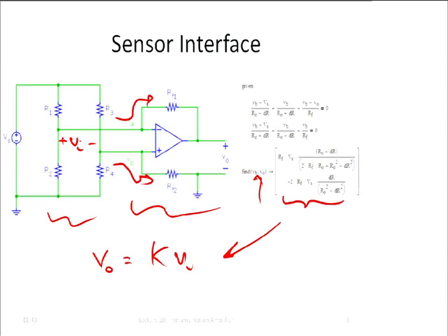Yeah. You put a big resistor there. Okay, we could make these two resistors really, really big, and then maybe the current that would be flowing would be smaller. Huh? Yes. Put a simple non-inverting op-amp at each point where we measure VI. You mean like this? Yeah. Okay. So he's got it right, right?